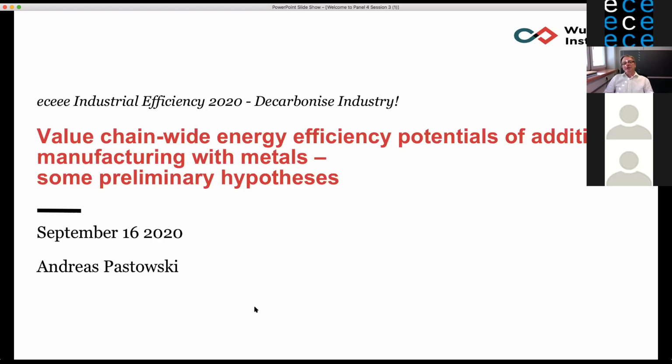But still, we have to be aware that 3D printing takes some time, and therefore it may not be the best processing technology when it comes to producing mass-produced items, because in that case you will necessarily need to be very fast in producing these items. Otherwise, the capital investment will be simply too high, and other things may negatively affect that kind of production technology.